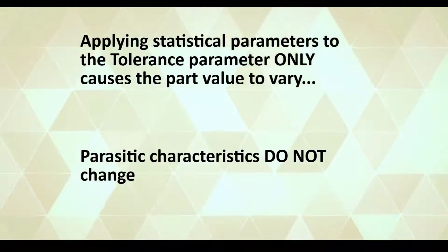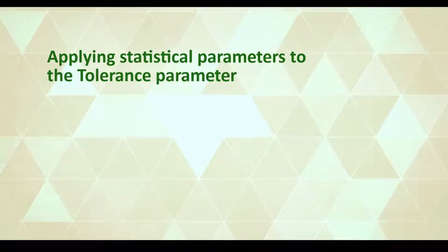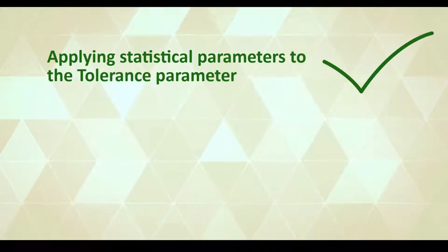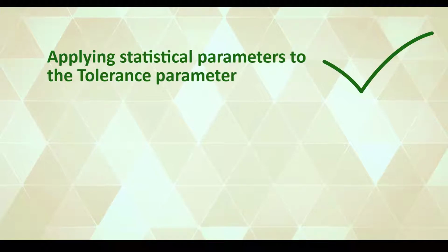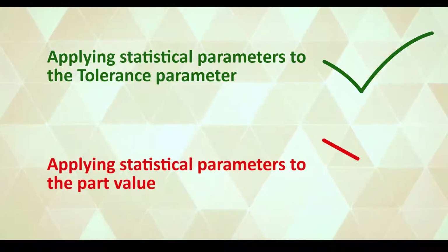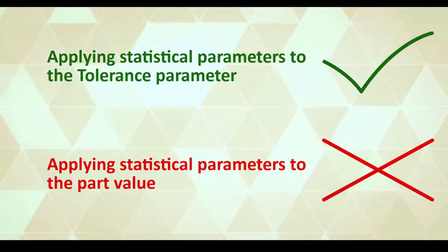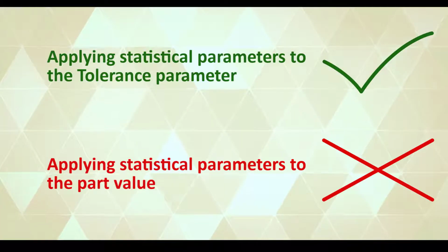So what this all means is that utilizing the tolerance parameter for Monte Carlo and yield simulations allows for a statistical variation of the part value alone. Therefore, the tolerance parameter should be used for these simulations.